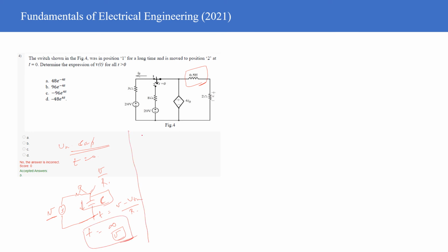For inductor also I told you in the second question. So initially there is no initial current flowing in an inductor, right? So inductor L, no initial current. And at time t equals 0, when it is connected via some resistance to a potential V, then the current will be equal to 0 at time t equals 0.